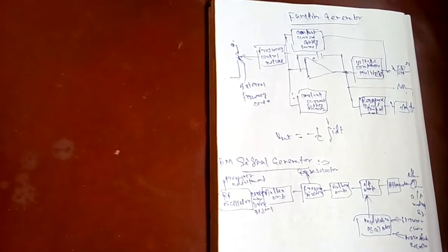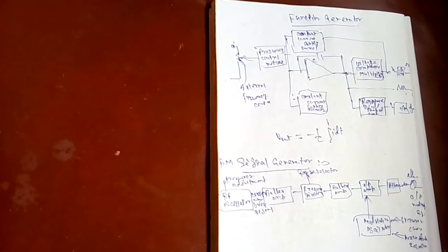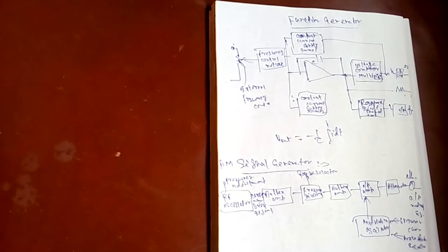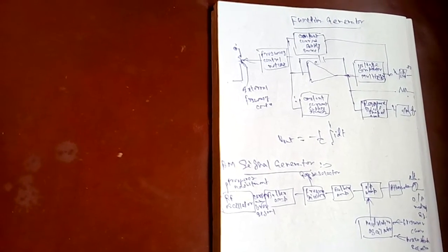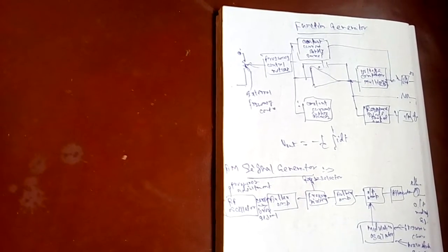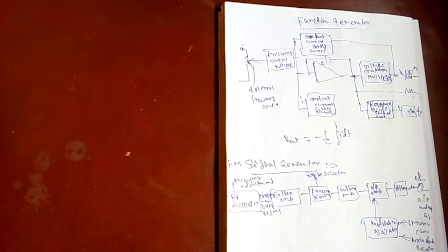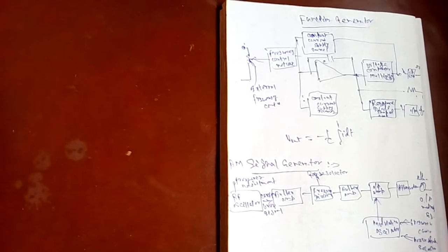Then the frequency stability of the oscillator is kept very high at all frequencies. These are the following stable conditions. The frequency of the output changes with the change of the supply voltage, so a regulated power supply is used. A buffer amplifier is then used to isolate the oscillator circuit from the output circuit, so that changes in the circuit connected at the output do not affect the frequency and the amplitude of the oscillator. Temperature also changes the oscillator frequency, so temperature compensation devices are used.